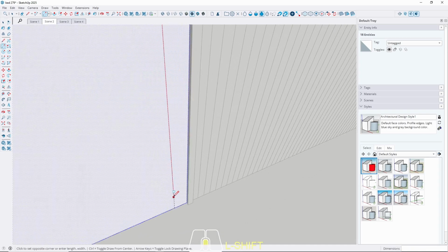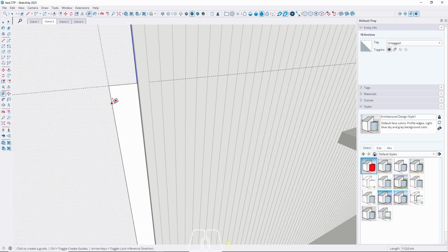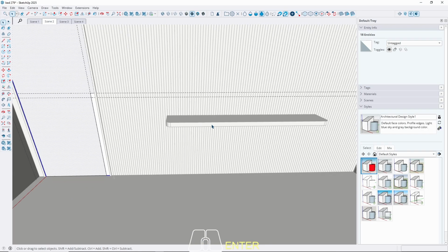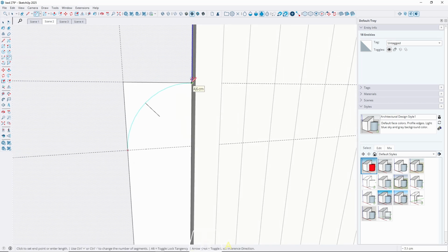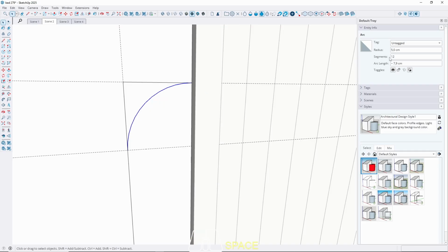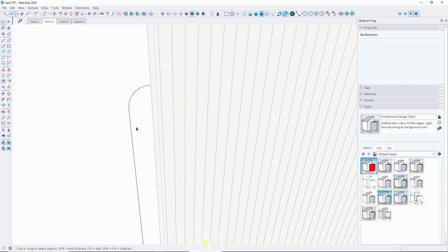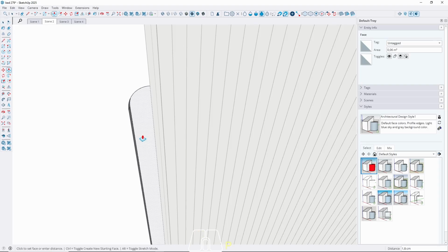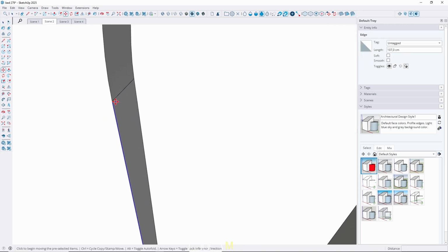And then make a groove and round it, so we have a unity from this shelf. We have a same design language. Give it 30 segment for a smoother line, then delete the guide, and then push it only for 1 centimeter, and then groove it.